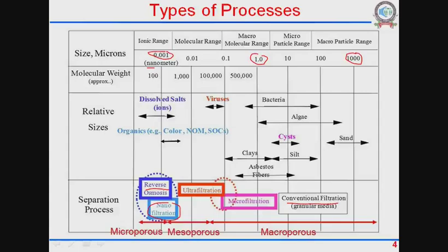Now if you look at sizes of molecules which are of the order of, say, enzymes or proteins, you have sizes between thousands to 10,000s or 100,000 molecular weight. Their sizes would be something like 0.01 microns, meaning 10 nanometers to maybe 100 nanometers, or even from 1 nanometer to about 100 nanometers. Then we would call that kind of filtration operation ultrafiltration. So recall just the nomenclature.